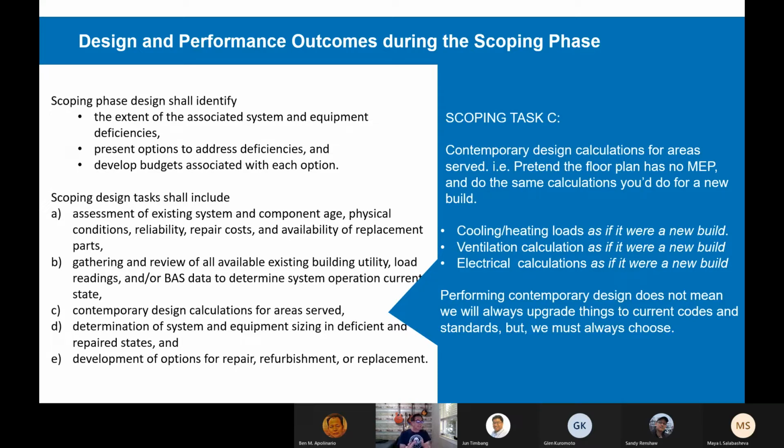Now, that does not mean that we're going to change the airflows in every room, but it does mean that we can compare the contemporary design calculations to the current state in the building. And there's going to be zones where we need more cooling or more heating or less cooling or less ventilation. We want to know that, and we want to be able to walk through that to see where we can make changes and will make changes.